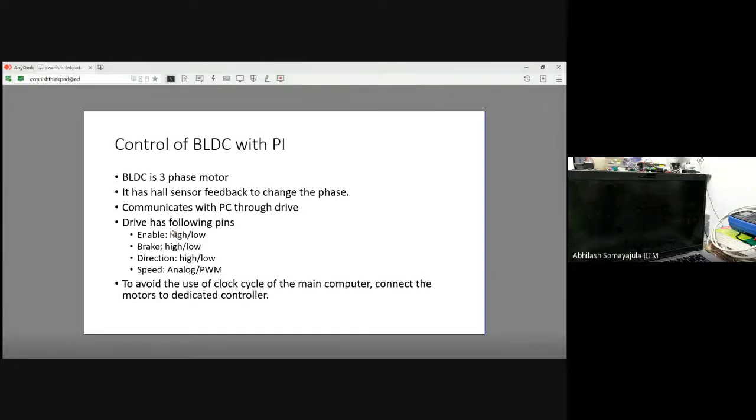For example, I just want to give this example because I'm using it right now. What I'm using is a micro PC, a straight away PC on a chip model. Now, if I want to communicate over I2C with the real-time clock or the MPU 6050, I cannot do that. I need something in between. But if I have a Raspberry Pi, I have all this as GPIO.